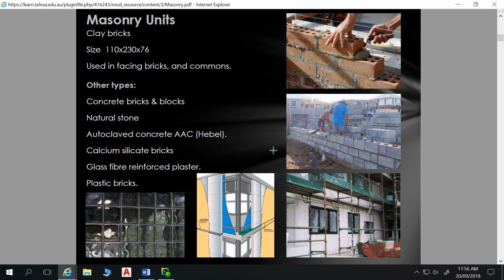If ever you do that, it's very important that the concrete is put in there in predetermined lifts. So you don't want to just fill the whole wall with concrete. If you fill the whole wall with concrete, particularly if it's bricks, then the bottom of that wall can blow out and you lose all your concrete out the bottom, make a big mess, and you have to do a lot of rectification work for your wall. So typically it's specified in 1 metre lifts. So you put 1 metre height of concrete in there, let that cure, let that harden a little bit, then another metre, then another metre, like that.